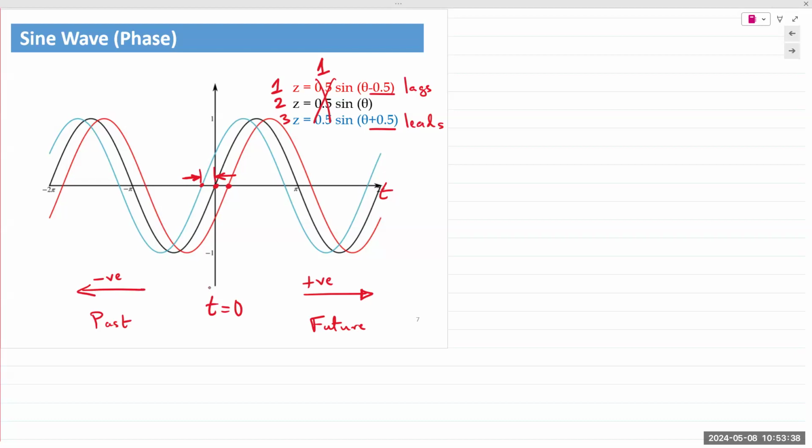And again, as I said, there's a reason we keep it separate, because we'll describe it as a vector. And for a vector, we'll need that phase angle. So before I go to the next one, let me ask you, we saw those waveforms, right? All of them are symmetrical about the x-axis, half above, half below. What is the average value of that waveform? 0, right? 0. But energy is still being transferred.